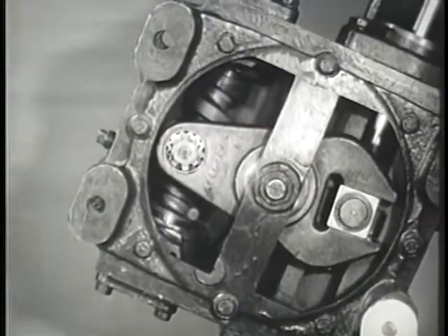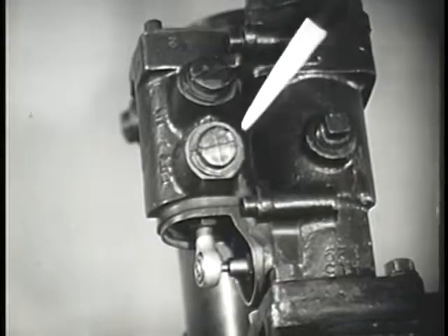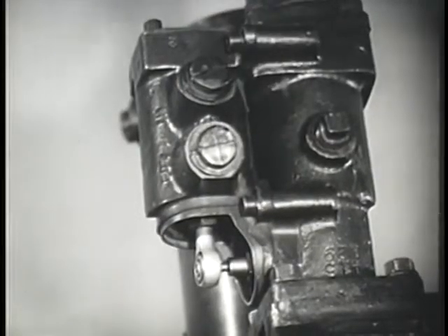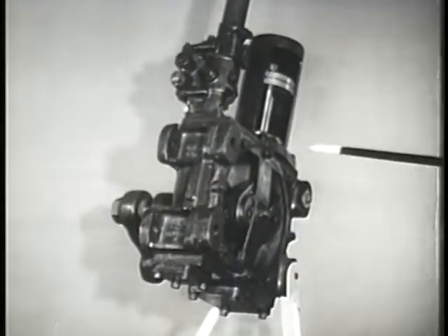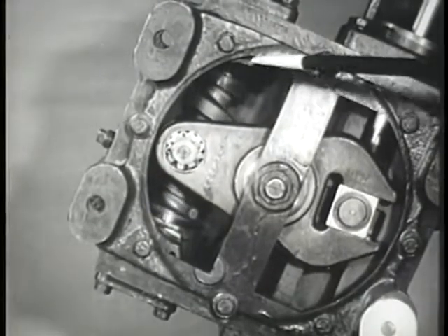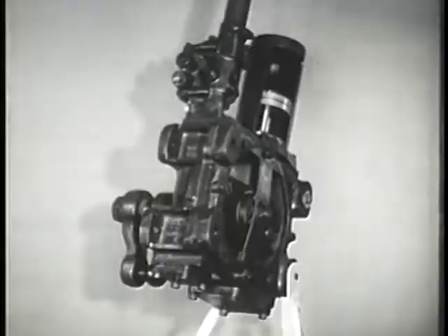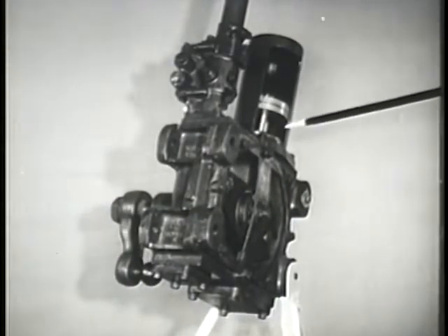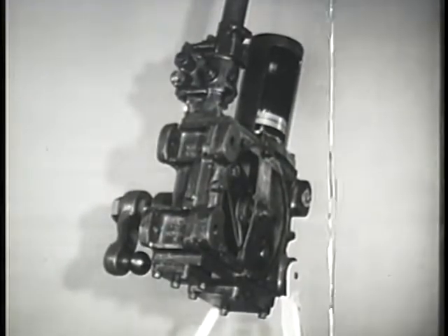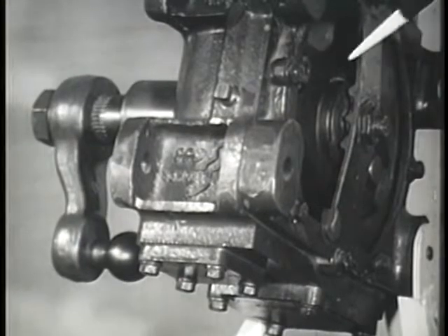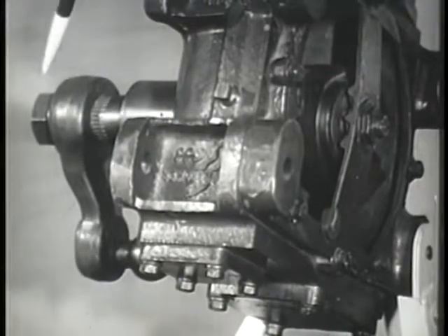In order for the hydraulic assist mechanism to operate, the steering cam must be able to move up or down to actuate the control valve. A spline connection makes this possible. The cam is held in center or neutral position by a spring at either end. The slightest movement of the cam results in a pressure differential in the power cylinder and an applied force on the pitman arm shaft and lever and the pitman arm.